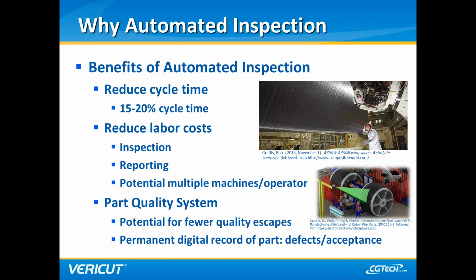The other thing that it does is it can perform and keep a permanent digital record of a part. So, as you're laying up a given part, you could track over 6 months, a year, 10 years, whatever it may be, how well that part lays up. And you can use this information to help determine when maintenance may be required on the machine, whether you may want to look at redesigning a part slightly to help it in manufacturing. So if you're always dropping tows in a single location every time you build a part, you could take that data design and see if there's something that can be done to improve that to help you out.